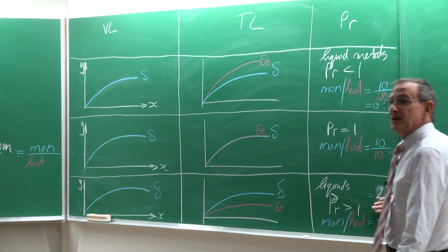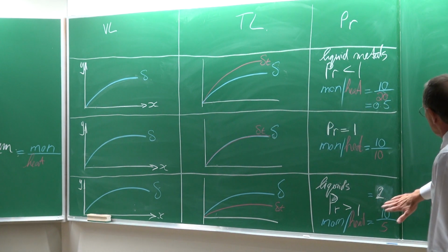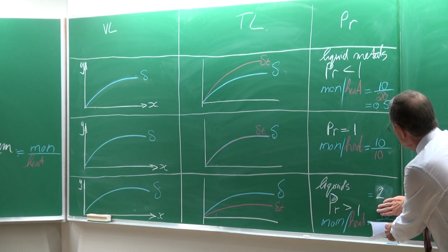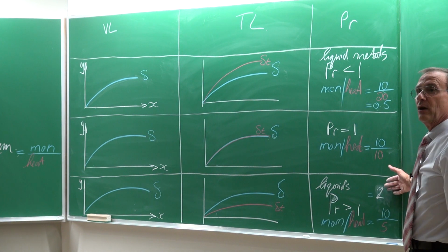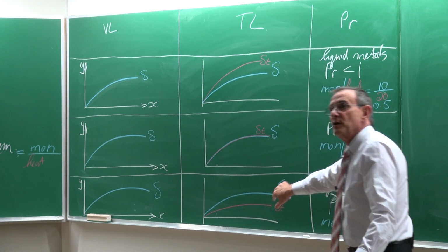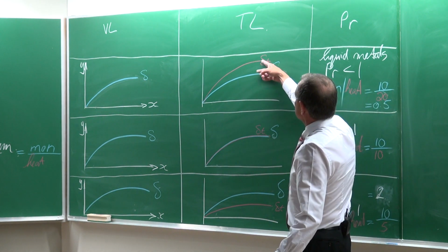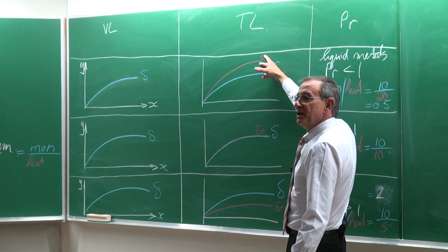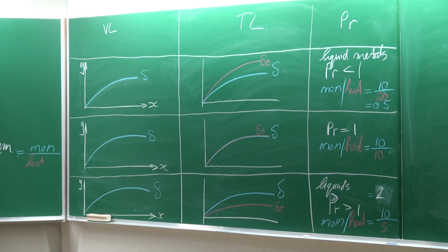So in terms of a relative value of the momentum diffusion, if the heat diffusion is smaller, then the Prandtl number would be larger than 1. So the heat diffusion is smaller than that of the momentum diffusion. And then, of course, in this case, it's the other way around. The thermal boundary layer is now thicker, while with a Prandtl number of 1, they lie on top of each other. I hope that answered the question.